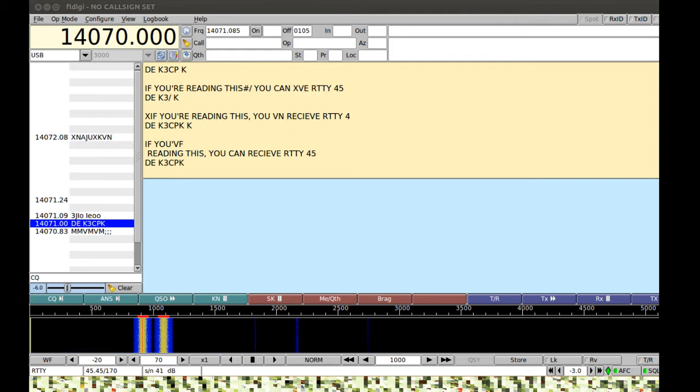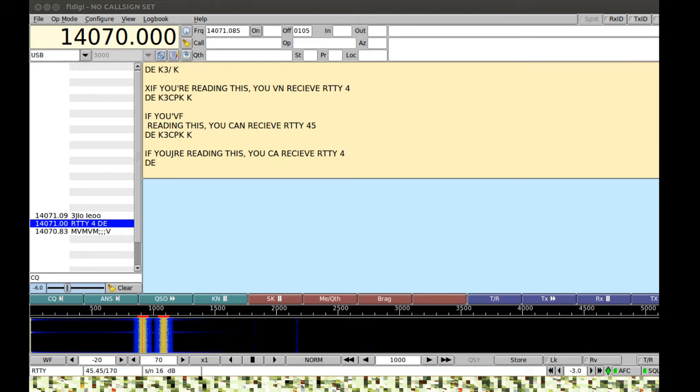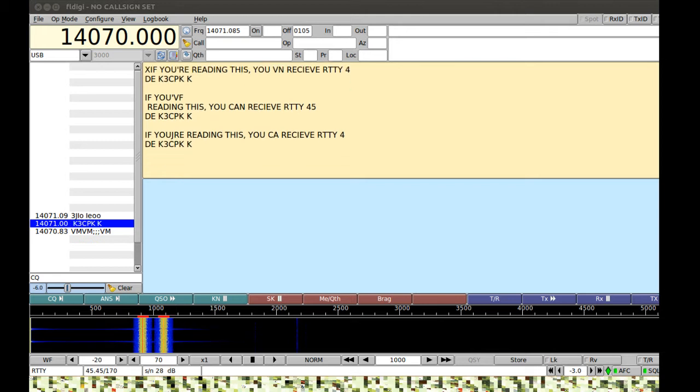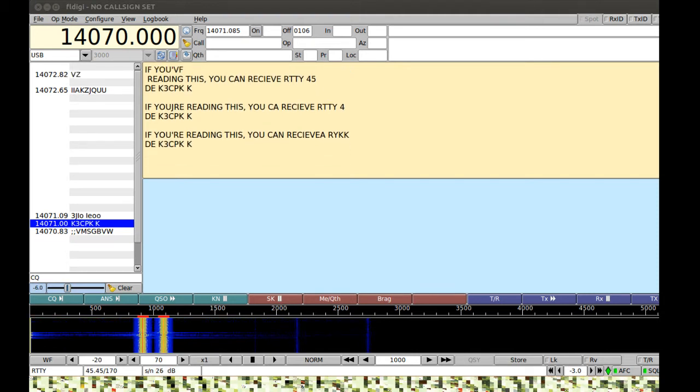I'm zoomed in four times on the waterfall and it's all easy. The tuners on each side, every once in a while the signal drifts, and you can see them wobble as they try to auto-tune to find the center of each one. One frequency is called a mark, and the other frequency is called a space, and that's basically a 1 and a 0, bouncing back and forth between them depending on the data.